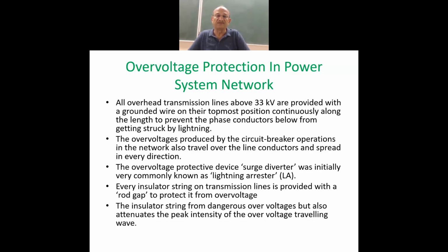The magnitude of switching overvoltages below 400 kV rated voltages was not a concern, not a damaging factor. So the basic insulation level was designed with the concept of the maximum magnitude of transient overvoltage produced by lightning impulse, and it was restricted to a certain level.